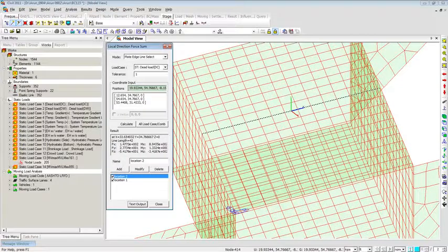So with this, this is what I wish to explain for the box culverts: how to extract the results using finite elements through the approach of local direction forces and cutting plane diagrams. As you can see here, result extraction is as simple as just cutting or drawing lines and hitting buttons and generating the text output in no time.